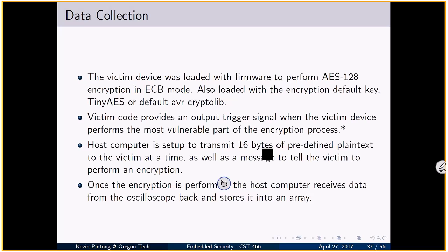We can figure out what it's doing. That is still a side channel attack. Same setup. With the AES, it might be a string, it might be a longer window that you monitor the code for, and you attack that section of the code. So, for example, if I'm looking to figure out what an XOR operation is doing, I'd look at that single XOR instruction. But with the substitution step, you might be looking at the store instruction, the load instruction, right? All of these may give you more clues. So it's a collection of instructions that you might be able to attack. Multiple data points leak information, but recall that the store is the noisiest.